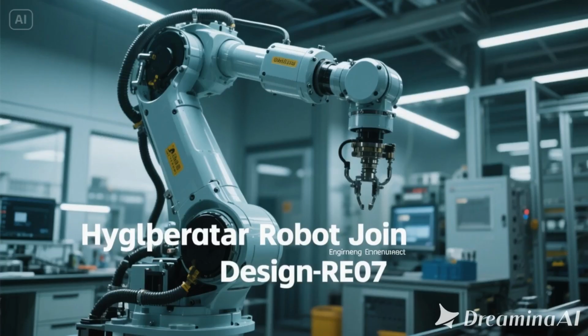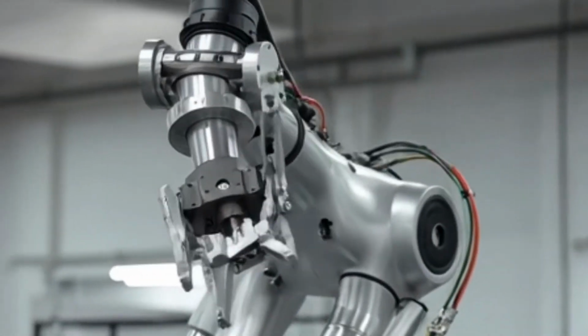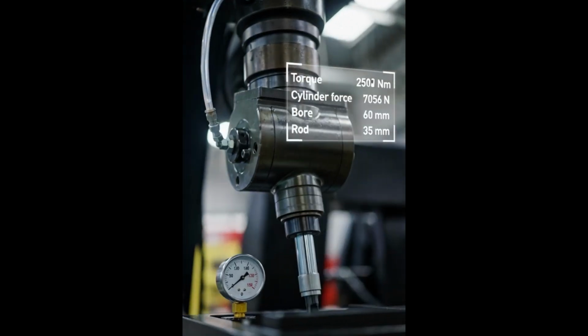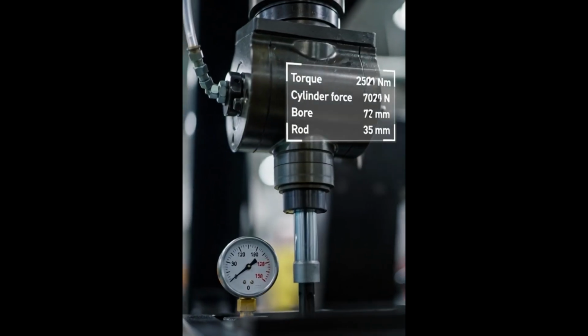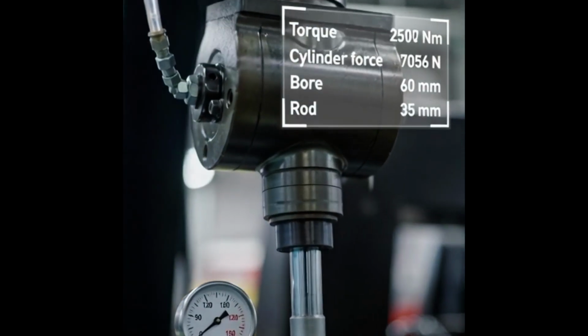Step 2. Calculating joint torque. Next, we calculate the torque required at the robot joint. Torque equals force multiplied by distance. So, joint torque equals load force times arm length. This tells us how much rotational effort the joint must produce. In our example, this gives approximately torque equals 2117 Nm. This is the rotational torque that our hydraulic joint must generate.